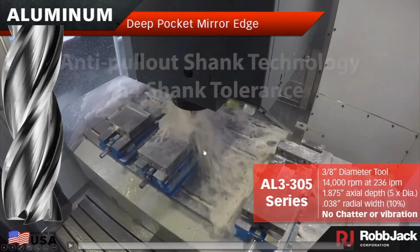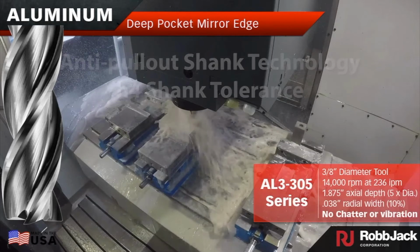So I'll pause that to talk about it. That was going 14,000 RPM with a 3/8 tool sticking out almost 2 inches deep. If you try to take a normal 3/8 diameter tool in aluminum, cutting at 14,000 RPM, 236 inches per minute, it would normally just squawk and squeal, and you would have the worst finish. Tons of chatter, vibration. You'd probably snap off the tools.